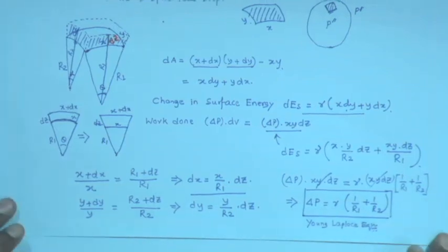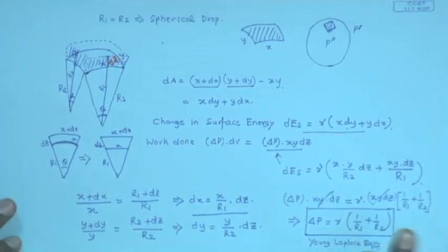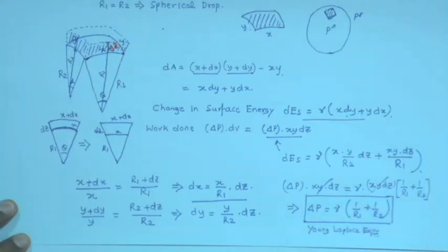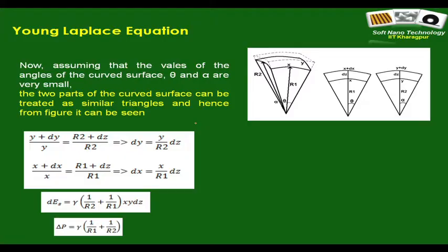So, you now see that there is some pressure difference across a liquid meniscus because of the effect of surface tension, and for an arbitrarily curved surface with, at any given point, the two orthogonal radii r1 and r2, the Young-Laplace equation in fact correlates the delta p with the surface tension and the local radius of curvature. This is a very, very useful equation. In fact, it can be used in many cases. It is important. I will just talk about a few examples very quickly.